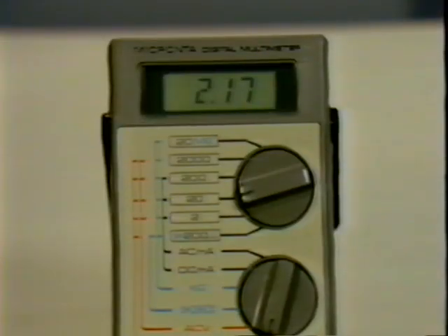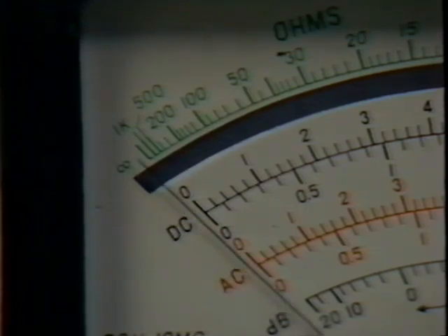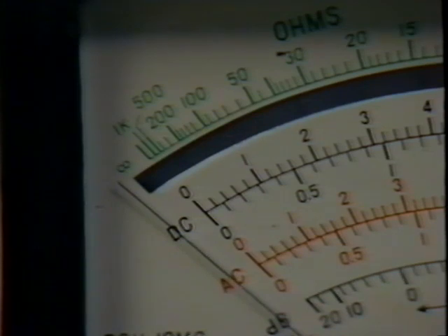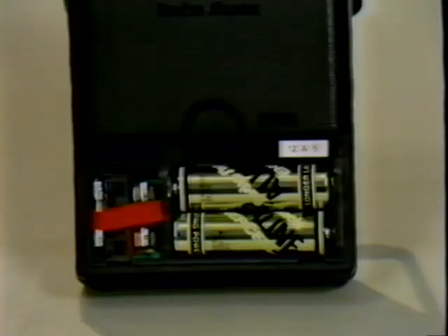The digital voltmeter can also display much smaller current changes than an analog meter can. These two factors make its readings extremely accurate. A final advantage that the digital meter has over an analog device is the ability to deal with reversed polarity. When negative voltage is applied to an analog meter, the movement jerks violently backwards and may be damaged. A digital meter would simply display the voltage as negative. The digital meter, however, has a few disadvantages.